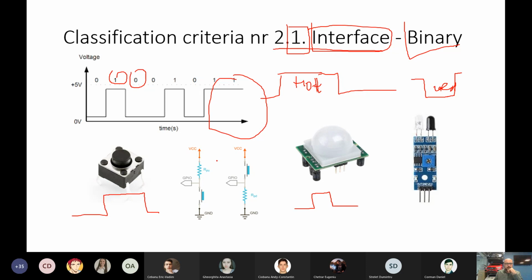Regarding the resolution, we can say, okay, how many values in the domain we have? In this case, we have only two values, and our resolution will be 2 on the power of 1, a 1 bit resolution. We can say we have a resolution of 1 bit or 2 values. We cannot have a resolution of 1, because we can have or not have, true or false. In this case, the lowest resolution will be 2.